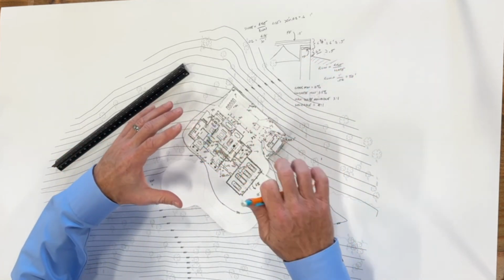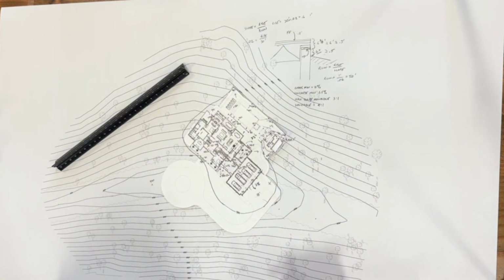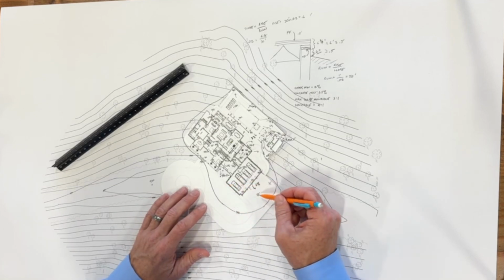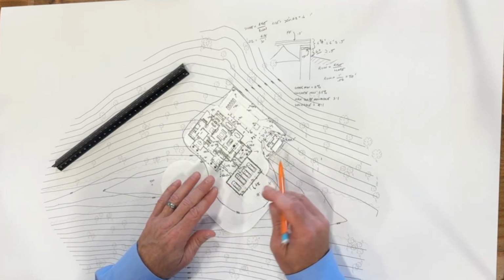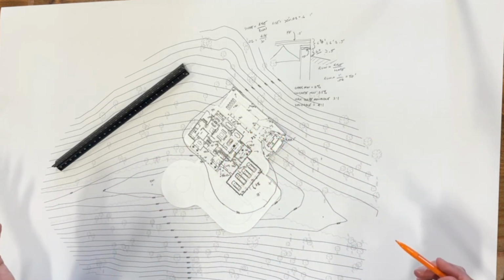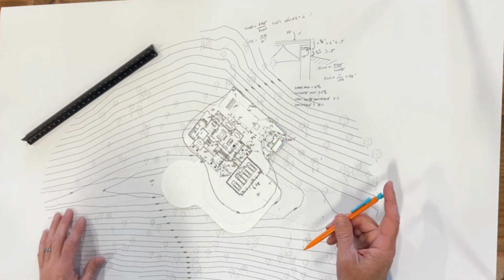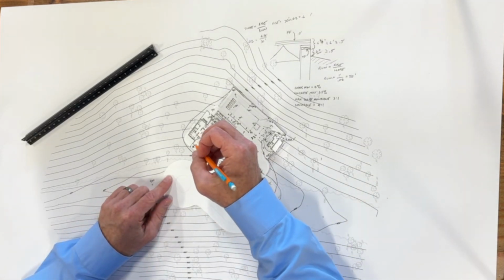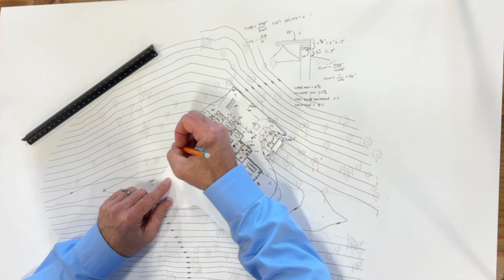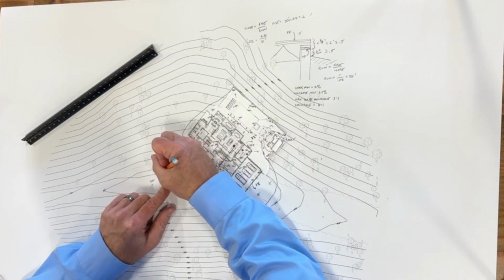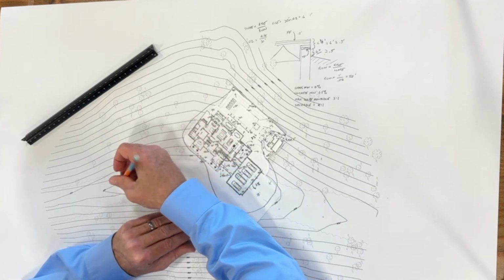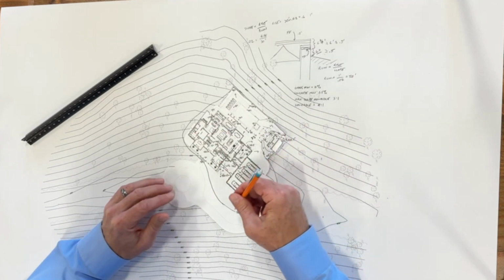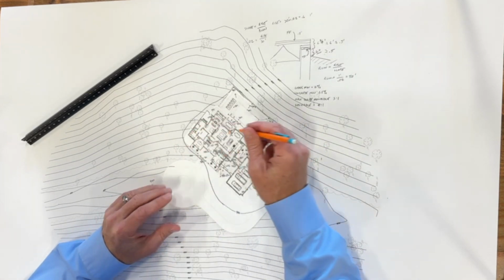So now we have this island all the way up, and we've established that all of these areas are going to drain at a minimum of 2% slope in all spots. Okay, what happens to the rest of the site? So now we start connecting into other contours. So here's a 939 coming across, and I like that it still goes downhill from the 940. So let's just make this 939. Actually, that was the driveway. There's 939. Here's 939.